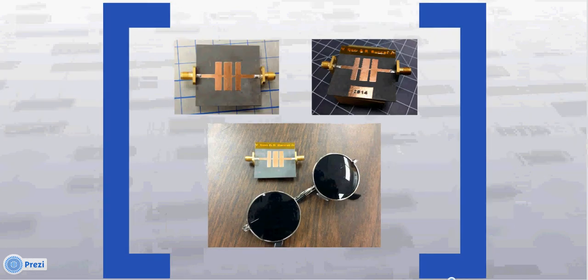Next, we have to carefully take out the extra copper pieces outside of our filter design. Once that was done, we place the copper tape on the blank side of the substrate. And then we take off the Kapton tape, and finally solder the connector onto our filter. This is the final product of our filter.